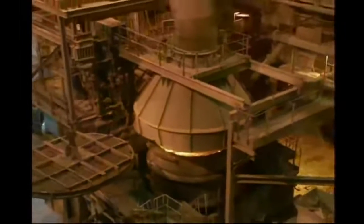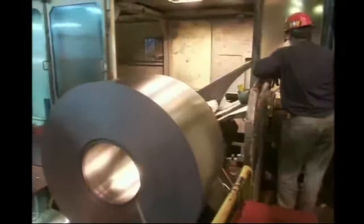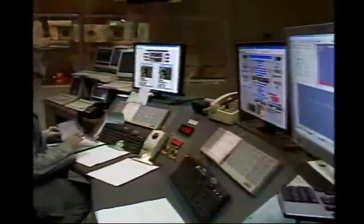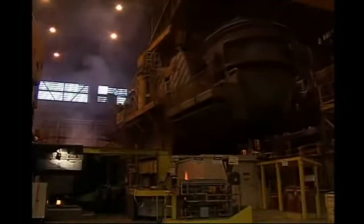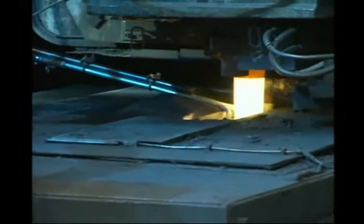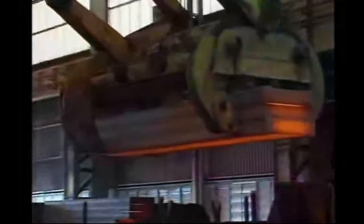Then, for most of our steels, it's on to the vacuum degasser, where they are made highly formable. The focus then shifts to forming and finishing, which determine even more of the steel's characteristics. The first step in this sequence is to position the ladle above a massive tundish or funnel that feeds a continuous caster containing molds that shape the steel. The molten steel, now at 3,000 degrees Fahrenheit, is channeled from ladle to tundish to caster, where it cools to a red-hot solid.